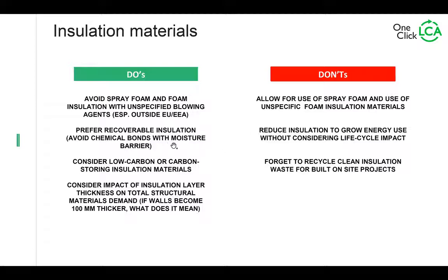Second, if you can use insulation without gluing it to the moisture barrier or to anything else, do so, so you can recover it, because it could be recycled and reused. Consider low carbon or carbon storing insulation materials. I will waive giving an opinion on that right now, because it really would depend on your location. Some locations do have a bit different supply. Insulation is a very local material because it's expensive to transport for most types of insulation.